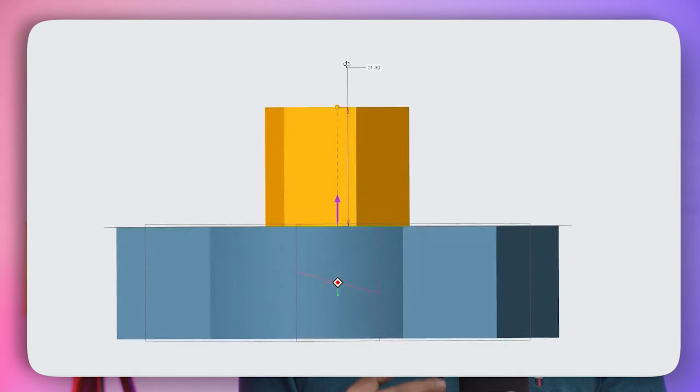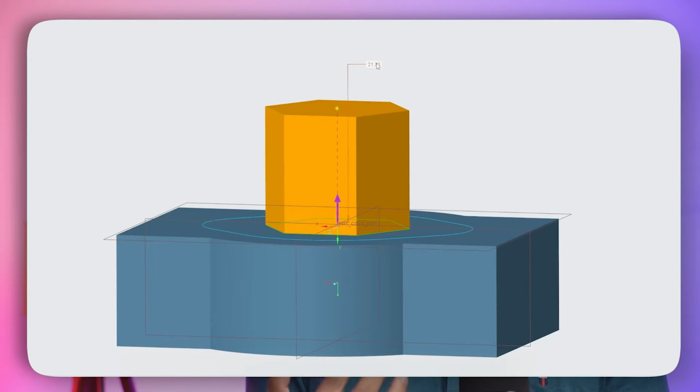And if I talk about PTC Creo Extrude, it is quite vast, as not only can you add material through it, you can also remove through that. So if I compare it with software like Solid Edge or Siemens NX, or there are so many, in those software, we generally have two different commands, for example, extrude and cut. But in case of PTC Creo Parametric, it is only one tool. And then there are so many variations and options. So let's see and understand them one by one. So without further ado, let's dive in.